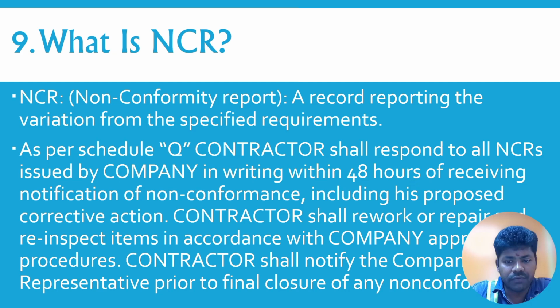As per the schedule, the contractor shall respond to all NCRs issued by the company in writing within 48 hours of receiving notification of non-conformance, including his proposed corrective action. The contractor shall rework or repair and re-inspect items in accordance with the company approved procedure. The contractor shall notify the company representative prior to final closure of the non-conformance.